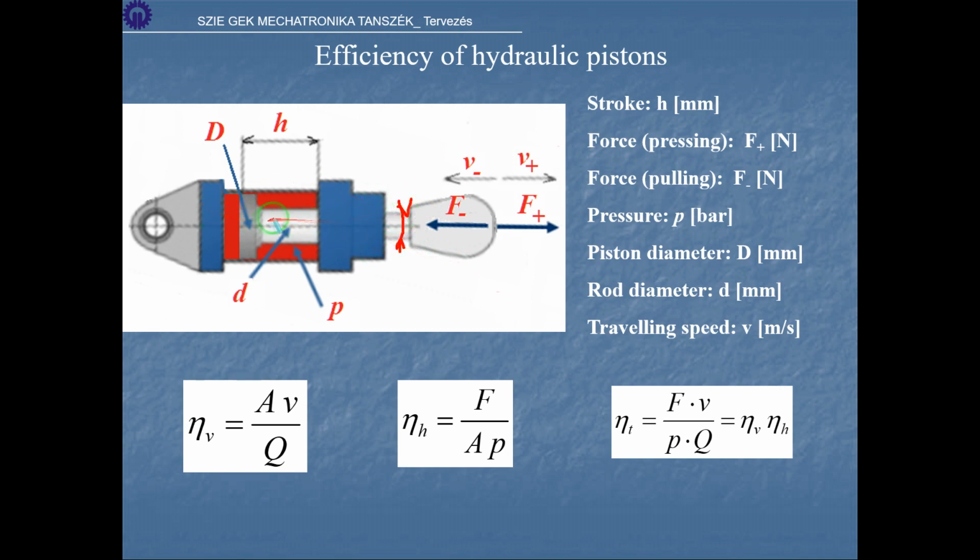Therefore the possibility of buckling this piston rod is much higher. Therefore we have to use a much thicker piston rod, and therefore the difference between the areas in the positive and negative chambers is very big in this type of application, so in hydraulics. So therefore we have to calculate these as well, and we will make some calculations with this.